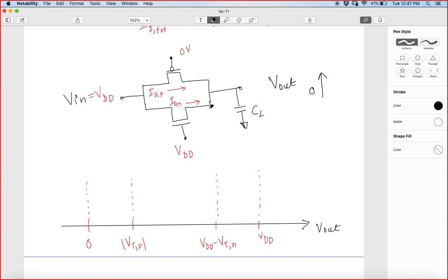So this is at lower potential, because of which I can treat this as the source in case of the NMOS, and it is as if the drain and the gate are shorted and connected to VDD. So my drain and gate are connected to VDD for the NMOS, and the source is connected to the ground.